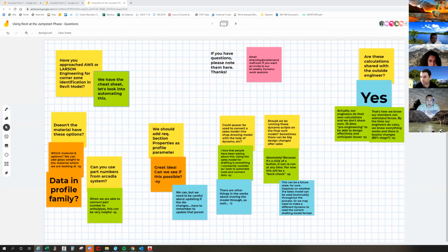Yeah, there's other factors, like the width of the units at the corners. Sometimes we may estimate it or see that it's just typical widths going to the corner, and then they want to merge those two, that smaller light at the corner. So now that changes the width of that mullion, and how the wind loads affect that unit and that intermediate mullion.